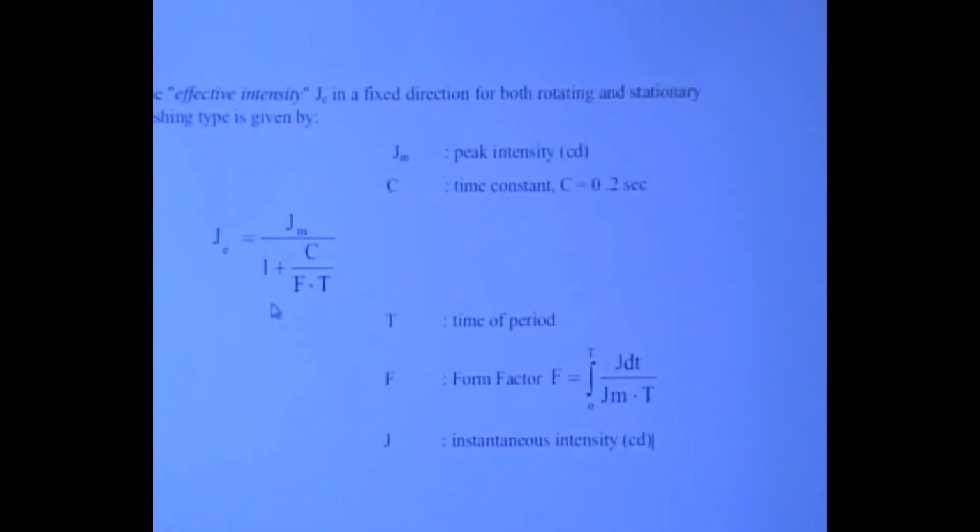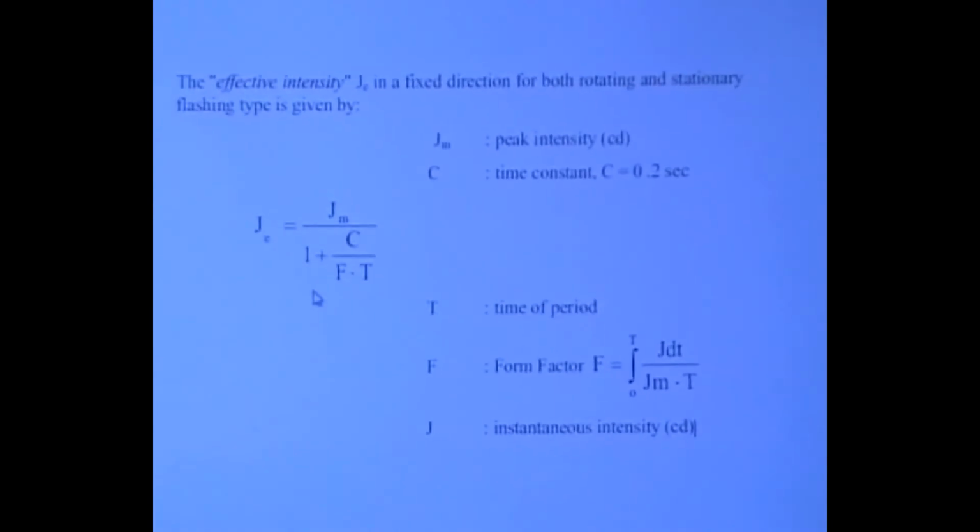So what we're asked to do is solve this equation in the regulations. And this gives us an amount of light, measured in candela. This is the other measurement of light. There's lumens and candela. And again, candela is almost the opposite of lux. That's lumens per meter or feet squared, depending on how far away. But it's not affected by distance because you measure it at the distance. If you measure lumens, you can calculate the lux just by the distance. You have to measure candela at the right distance because that's just the way it works.